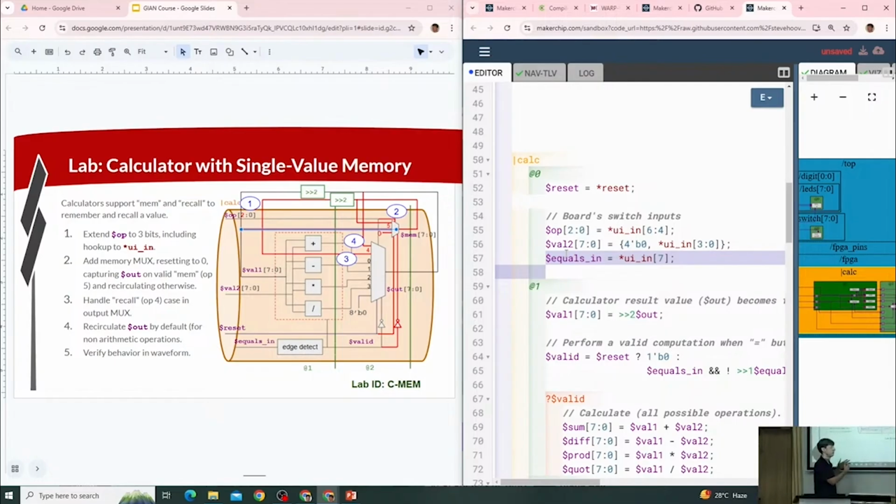So when you distribute an asynchronous reset and then a clock comes along, some places see that reset, some places don't. And there's no guarantee that you're going to see it the same every time. So there isn't one reset flow. It can happen differently in different places, and there's no way to verify all those combinations. If you create a synchronous reset in one place and distribute that everywhere consistently, there's only one reset sequence.